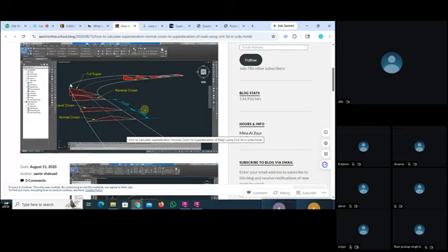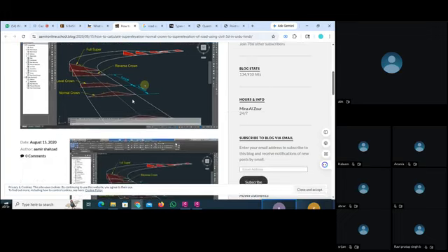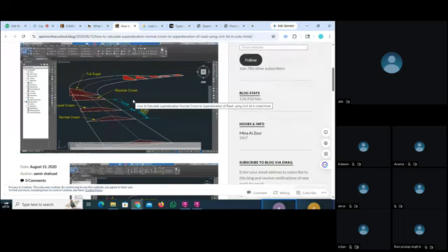So what do we have to manage? The outer edge of the road and the inner edge of the road. We have to keep the outer edge higher than the inner edge. That is because of the force that pushes our vehicle outward of the road, so it will be manageable; it will manage the centrifugal force. So this is the slope created here in a super elevation. This is the type of super elevation.